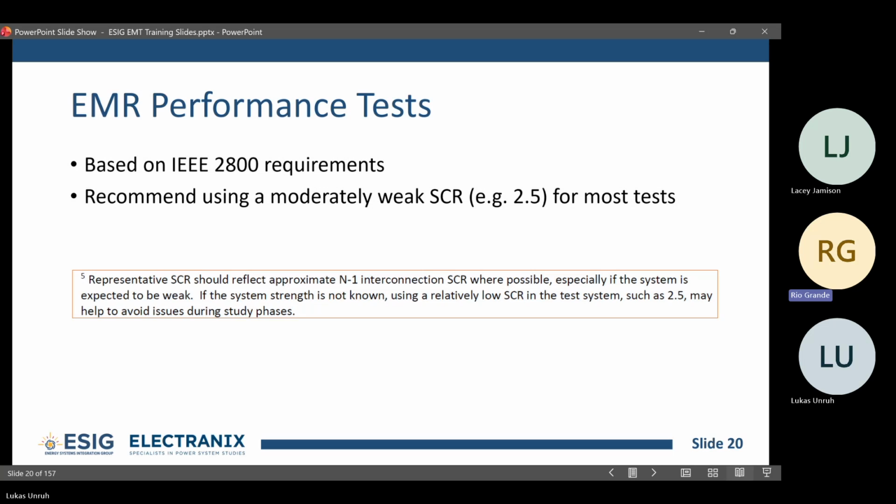I remember back, before all the renewable chaos, there was some definition of whether you're a weak system or strong system by X/R ratio. Back then, I think the number was 10 or something. I just wonder if there's a study behind that, or whether 5 to 6 is just common, but not actually for weak systems. Right. It doesn't necessarily mean you're in a weak or strong system with your X/R ratios. It doesn't necessarily say a lot about the strength of the system, I would say.